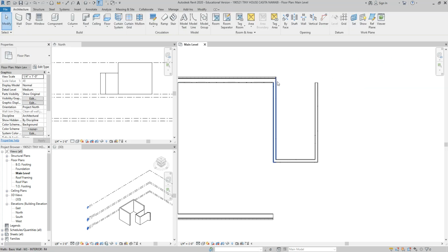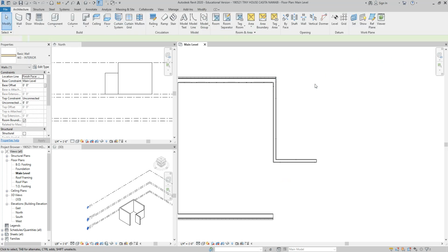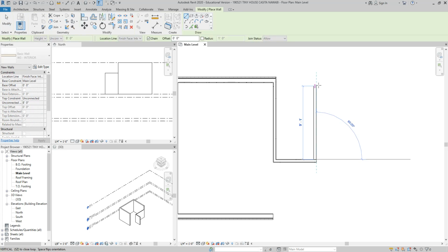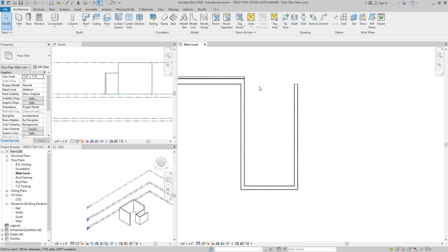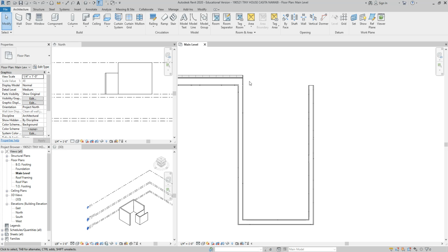And then I should be able to, I'll show you real quick. When I put in this last wall, it kind of snaps to where the other wall finished. And what you can do here, there are a couple options. Do you guys remember the shortcut to kind of bring two things together? It's not the fillet command. It's TR. So you click on the two things you want to connect. So TR, and it pulls it up. Let me show you one other way. And I'm going to wait just a minute so we can do them together.